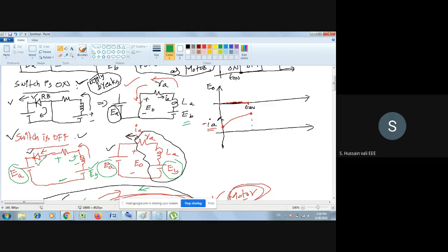Yes, you can say like this, that actually the motor is running in one particular direction, say for example clockwise. As the current gets reversed, the electromagnetic torque will get reversed. So when the electromagnetic torque gets reversed, and the load torque is in the opposite direction, obviously the resultant torque on the wheels will be less. As the resultant torque on the wheels will be less, the wheels will slow down. We can say like this.